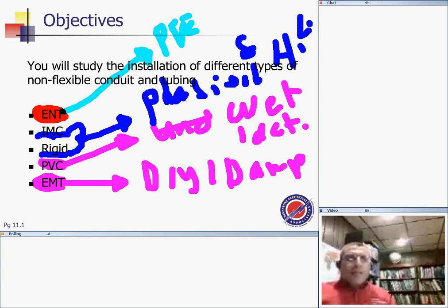For all other applications, guys, your conduit of choice probably will be a metallic conduit, and 90% of the time it would probably be EMT. Any disagreement, any correction? Probably 90% of what we do, we can get away with EMT conduits. When you're underground, probably 90% of your time is going to be PVC, schedule 80 or 40 will get you there. Any comments, guys? Any questions?